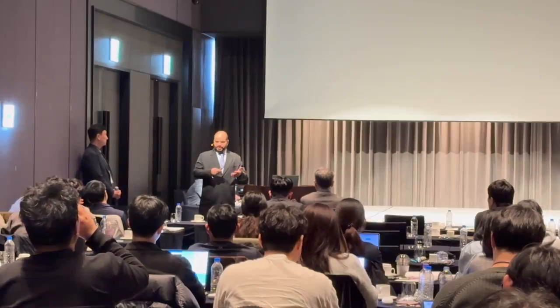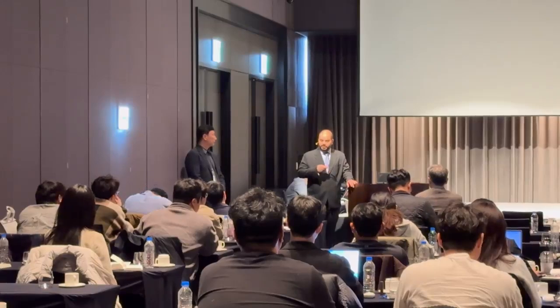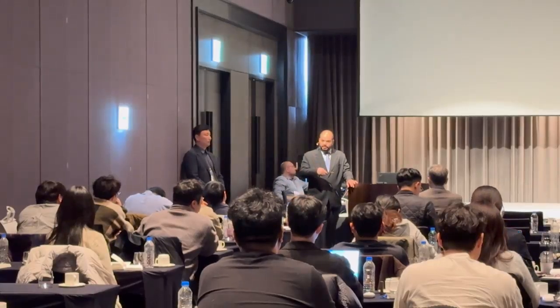So in that case, can I use this kind of thing as well using this Barracuda or other conventional tools you have? So deposition on particles is something that you can model within Barracuda. Now, exactly how that deposition happens, as you said, can vary. It can be through some sort of a chemical reaction, or maybe some other conditions for the deposition. But to model, yes, you can model. In fact, deposition happens and particles actually grow in size because of that deposition. So that is something that can be modeled within Barracuda. Maybe we can talk more about it to see how exactly you want to implement that. Again, maybe we have to implement it through a user-defined way, but just to know that deposition is accounted for and can be modeled within Barracuda on solid particles.